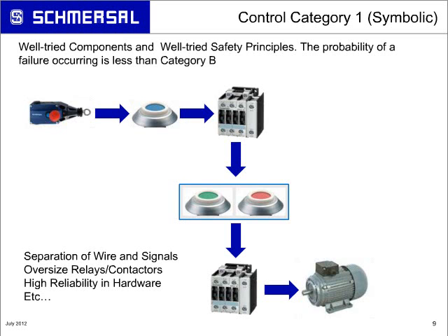That device has to come back and be wired into a control cabinet, into your master control relay, your enable relay, whatever your circuit is designed to do. In doing that, typical installation, you route two wires, your feed and your return, whether it's in the same cable or conduit or trough, going back to the control cabinet.